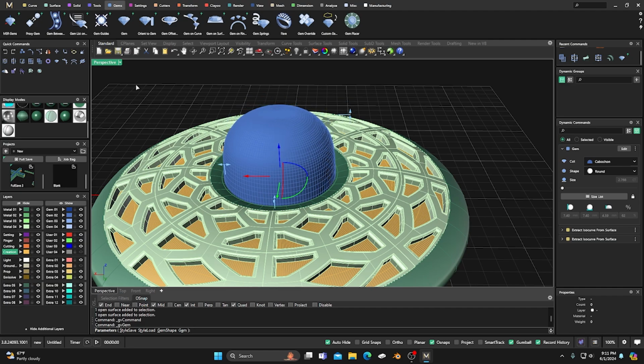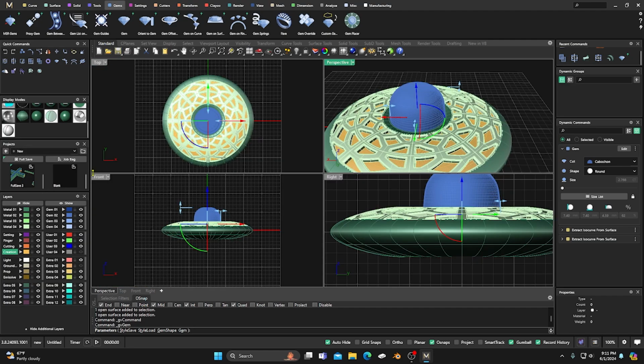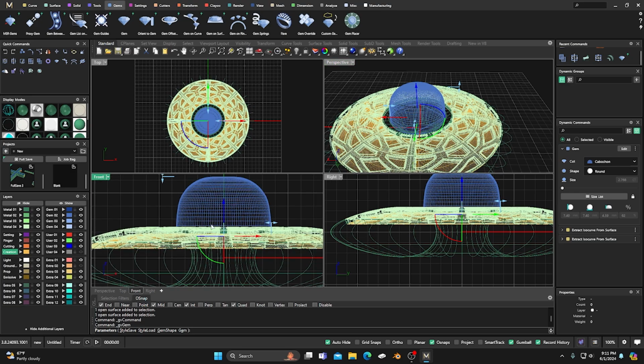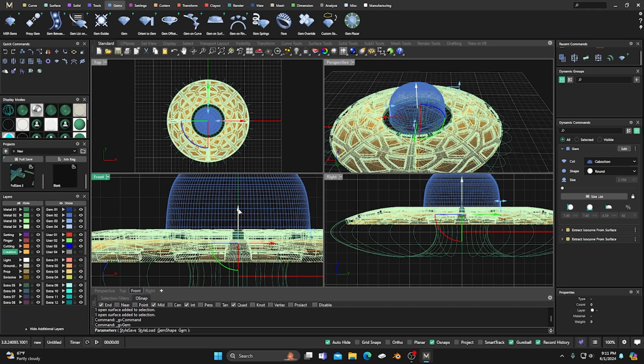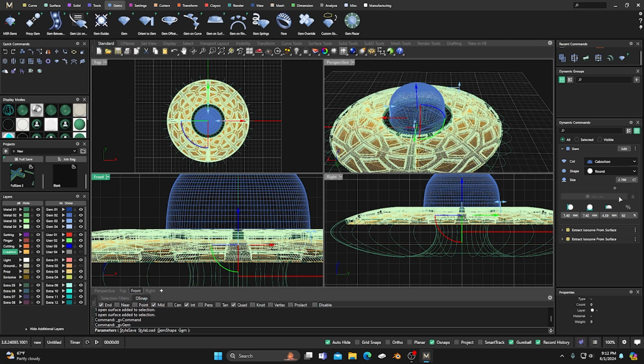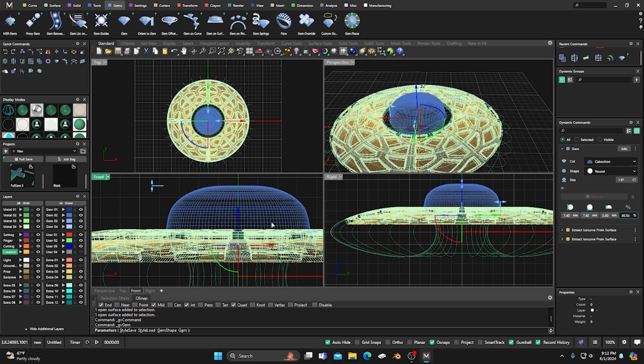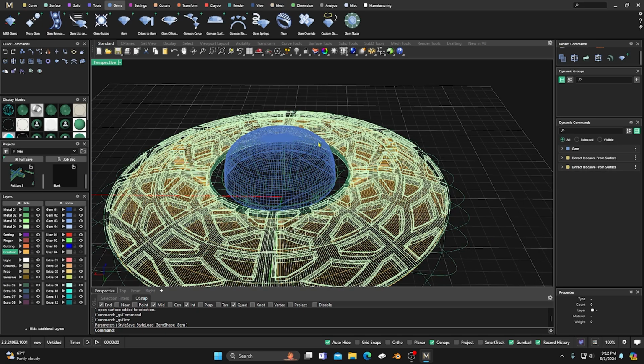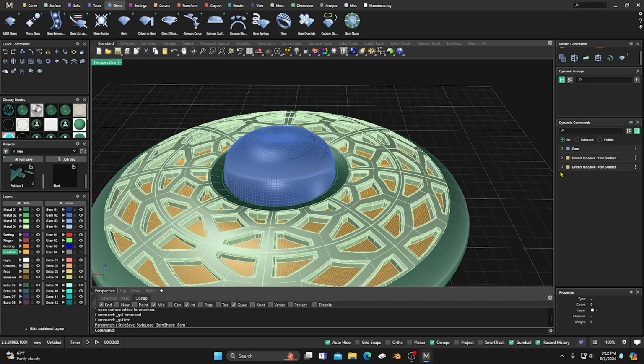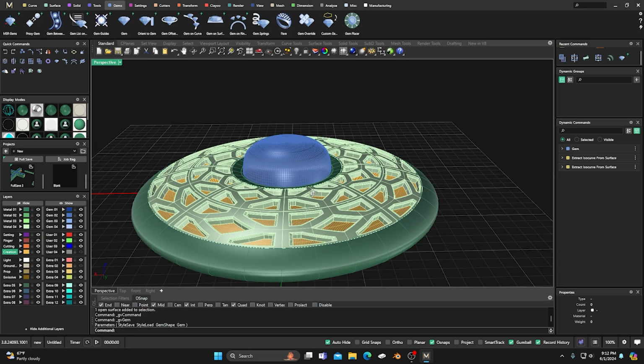So first let's kind of get it the size we want, something like that probably, and then we'll bump that down in there and maybe go to perspective or front view and kind of see how deep we have it in there. Maybe a little bit more. That red arrow there, right? Something like that maybe, perhaps. But we can come over here and we can unlock it right here. Just click on that lock, and then we can go to height here. Go in and click, and we'll just type it to a 3 and then hit enter. So it drops it down, maybe more of a shape that we want to use, right? So you can adjust that to any size that you want or whatever stone you're going to be using.